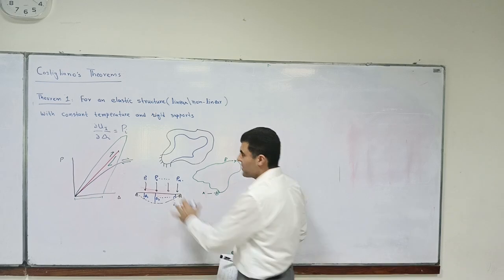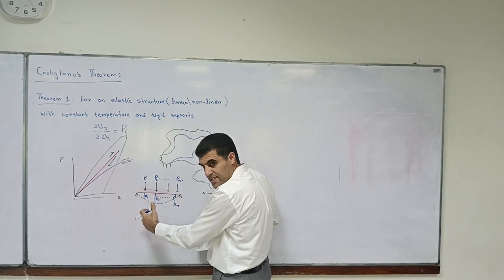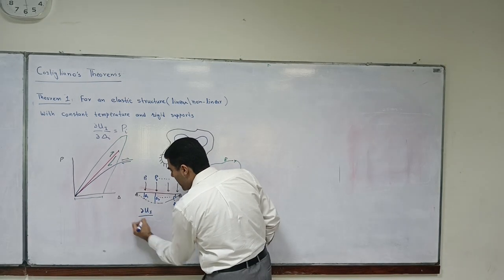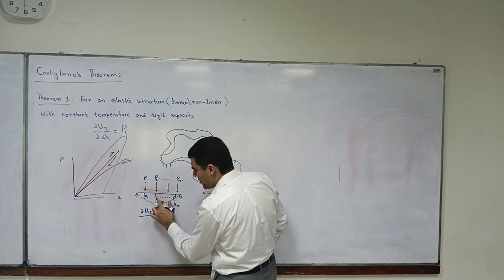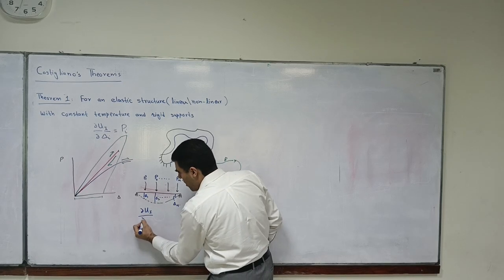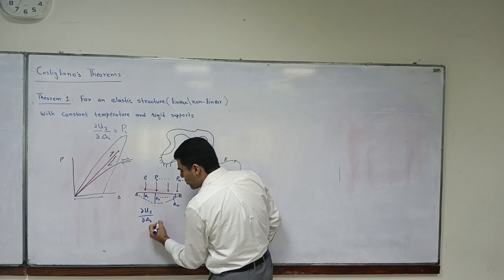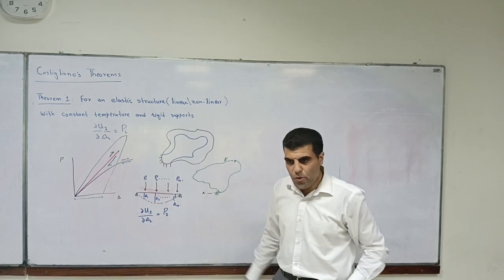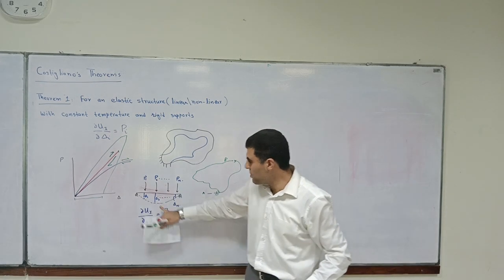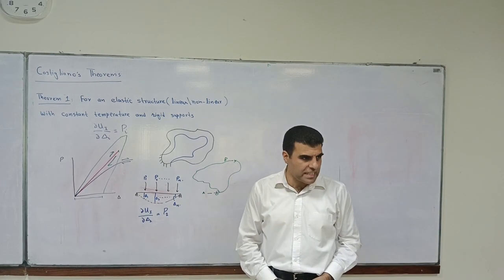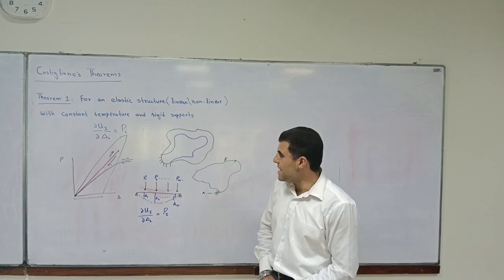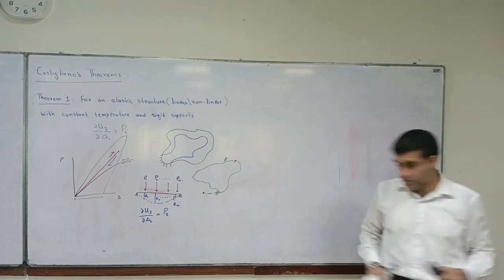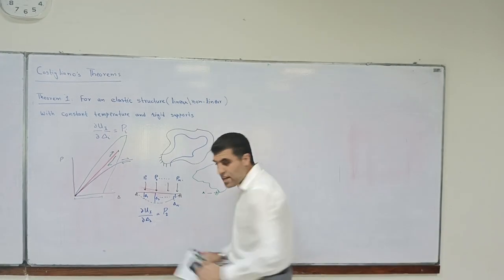That will come later. But if you take the internal energy of this system and partially differentiate it with respect to a certain deflection, say delta 2, you will get the load P2, which is responsible for causing your deflection delta 2. This is called Castigliano's first theorem. Now how is this derived? That we will discuss. Any questions so far?